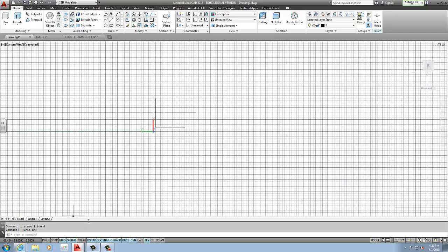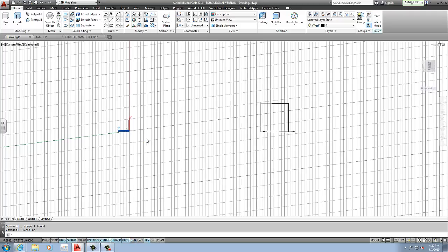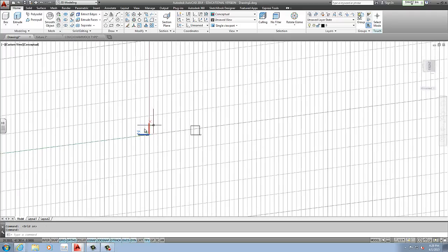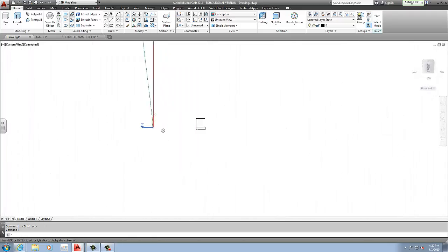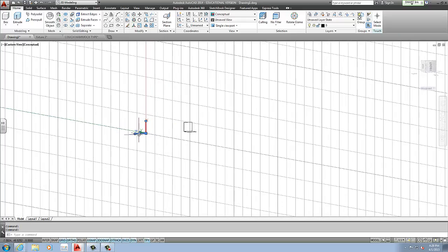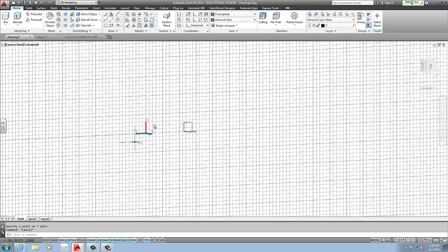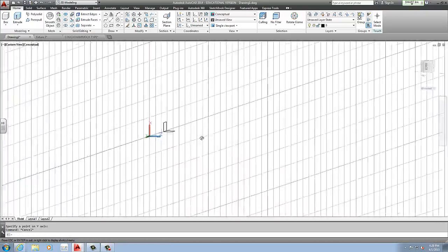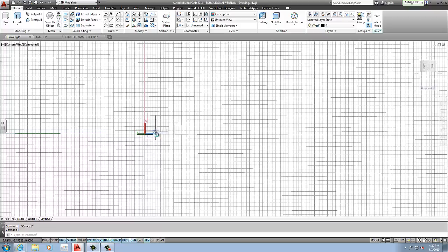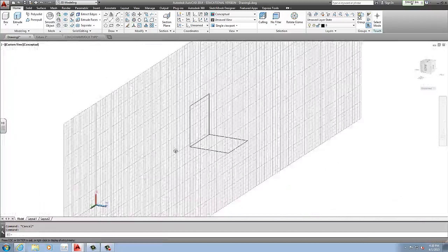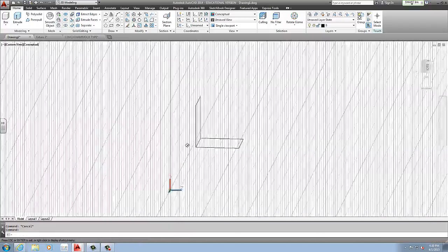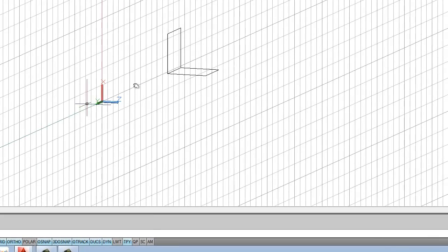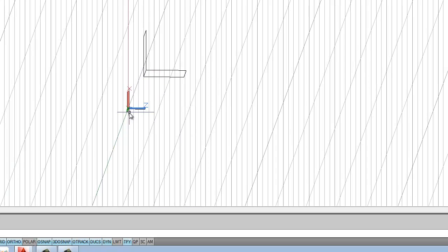I could also show you a grid. Basically, this grid specifies where a drawing is going to be placed. You can see I'm rotating around; that's where my grid is. Now if I had X and Y facing this way, then you can see that my X and Y surface is here, which is completely different based on the drawing that I just created. So keep that in reference, that way you'll know which way to set up your UCS to draw the correct lines.